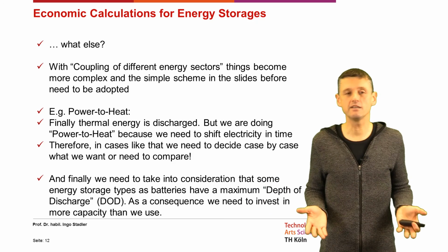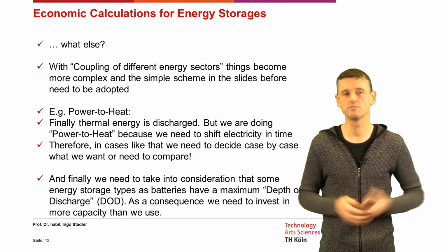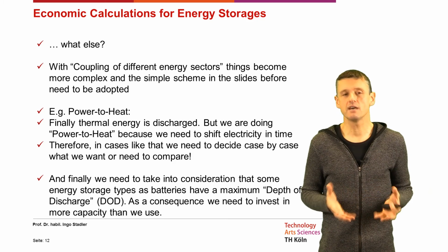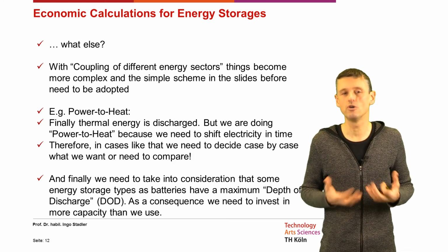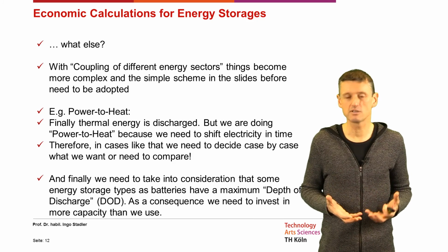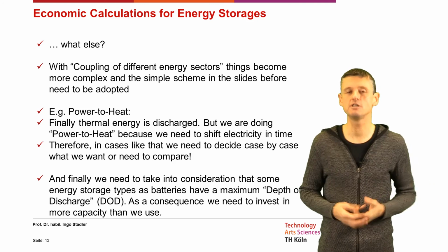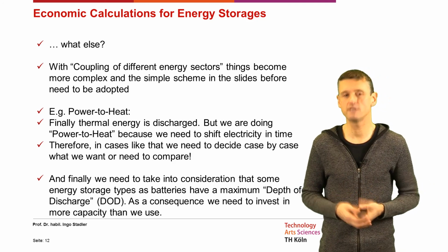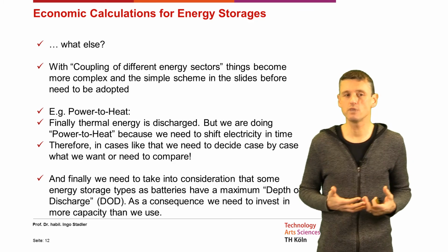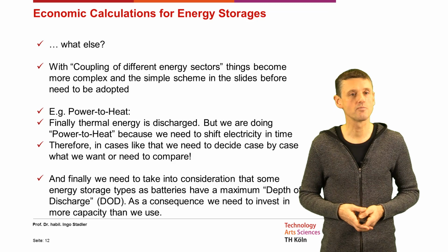And finally, we need also to take into consideration, when we talk about the investment costs, that we have energy storage types where we cannot use all the capacity. So sometimes we talk of a so-called maximum depth of discharge, DOD, of a technology. And as a consequence of that, we need to invest in more capacity than we in reality use.